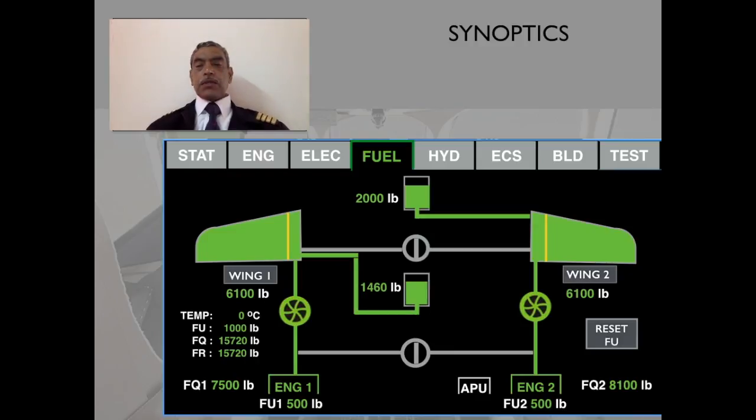And fuel used is also shown as the aircraft uses fuel, and the crossfeed option. When the pilot uses the crossfeed, then the status and the display will change accordingly. And of course, there is a push button with which the pilot can reset the fuel used before the flight if it has not been reset by the aircraft system.